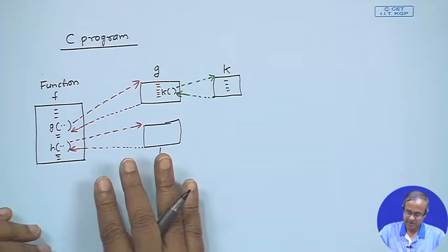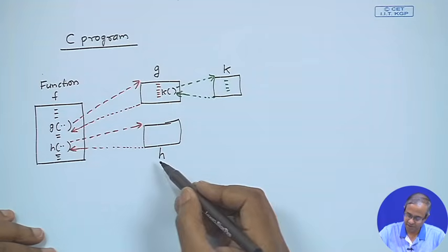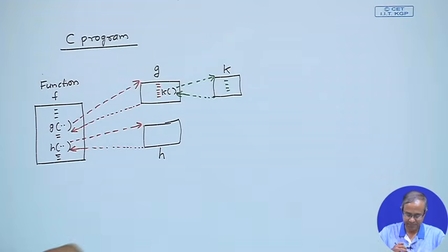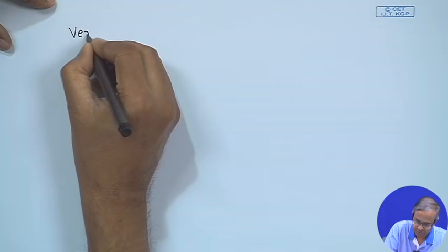So, in a C program, irrespective of how many times you call the function, the size of the total program does not increase, you are simply calling one function from another function. Your program code is not increasing in that sense, but in Verilog the concept is slightly different, because here we are talking about hardware. So, in Verilog we have the concept of modules.